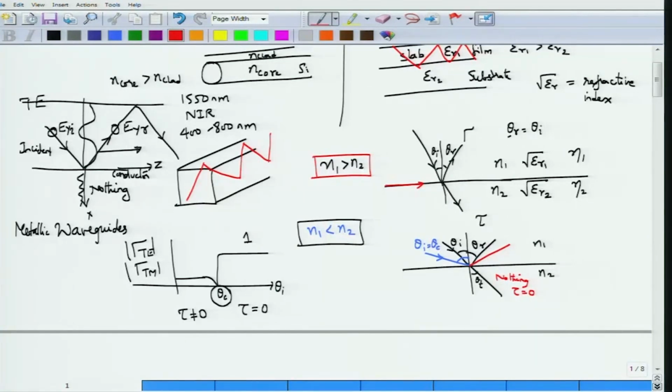Okay. Now let us say light has been incident somehow. Now light is getting reflected. What happens is, if I take another plane like this, at a certain distance, whatever the distance, let us say this is the distance d that I am calling, which would be the slab thickness. What happens now is that this red line, which represents the reflected ray from the lower interface, would come and hit the interface at the top. Now if the refractive index of the top medium also happens to be n2, this is called a symmetric dielectric waveguide, which is what we are going to consider in this example because of its mathematical simplicity to analyze.